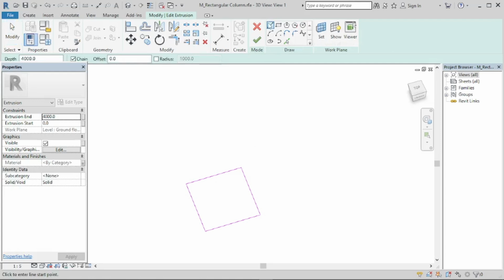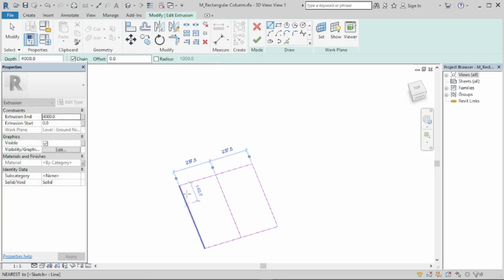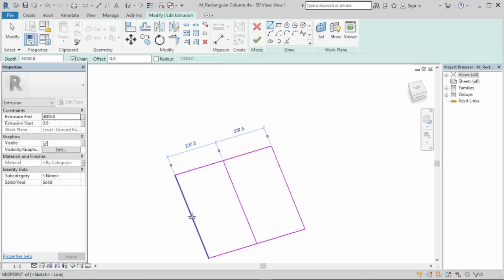So we can come here to the edit tool and pick a line, and once you see it snap with a triangular snap, you can just stop there and click on it and take it down to this place. Now we've got the center of this line. Now I want to get the center of this other line, so we can get the midpoint here. We come to this line, get the same triangular snap, and when we get it, we click on it and take it down to that place.